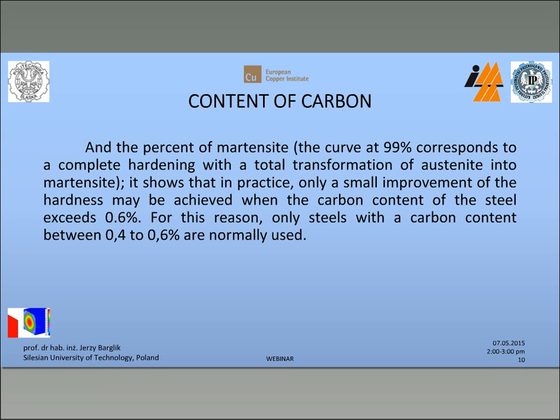We will see at the next slide in a moment that the content of carbon decides the quality, the percentage of martensite structure, and complete hardening. So carbon content between 0.2 and 0.6% is normally used.